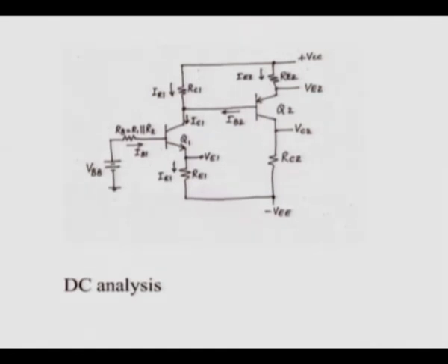In this case we see that they are cascaded. You can think of this as direct coupled. You can also think of two stages like common emitter, common base or common collector being isolated from each other through a capacitor. That way you could consider them much more easily because each stage then would be independent.